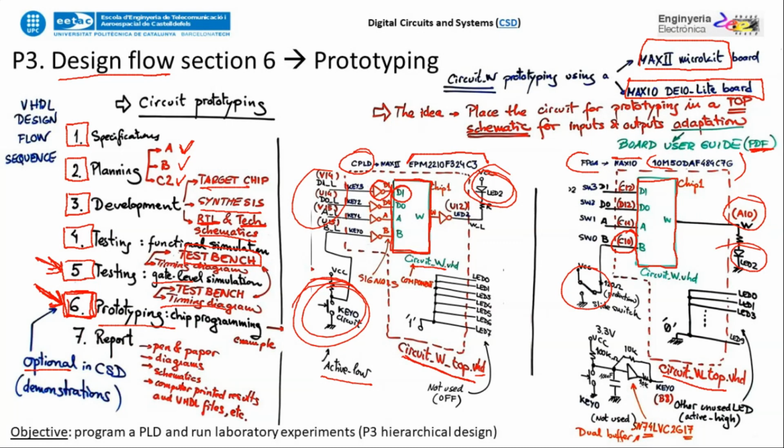So this is what you have to take into consideration in this video recording, so that in the end we will try that for 2 different boards, meaning that you can do that as many times as you like. Basically, it's going to be continuing the Quartus Prime project, but now adding the information of which pins you have selected as inputs and outputs, and finally generating the configuration file, POF or SOF or bit, depending on the tool extension, so you can download that file for real in the board and see what happens when the circuit that you have invented runs for real. So let's go and proceed with the recording.